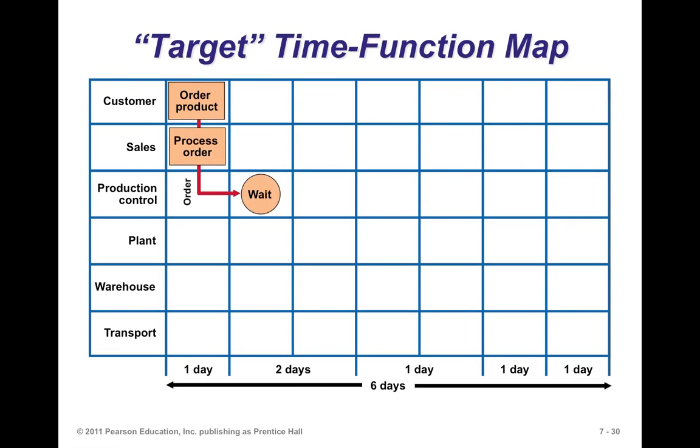Down to 6 days, if you look at this now, you could see how you've cut down the order lead times to 1 day, the wait time in print to 2 days. And then over here, you've removed all those steps that move and everything. In between here, you have some work in process inventory, but it's only 1 day's worth of that. And then you do the extrusion. You could actually go from 52 days to 6 days. That is a major achievement.